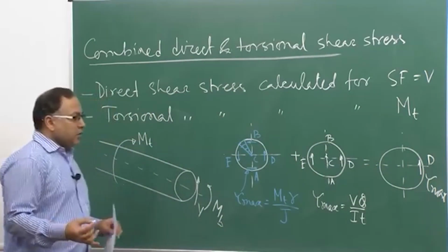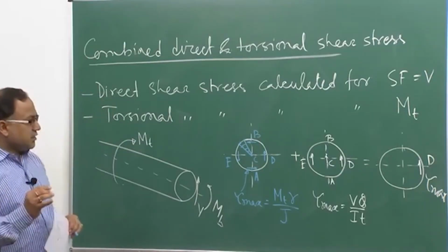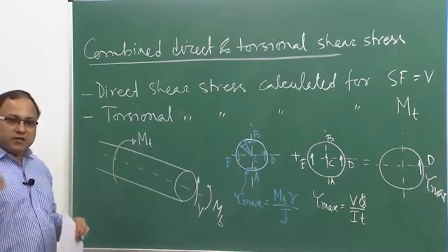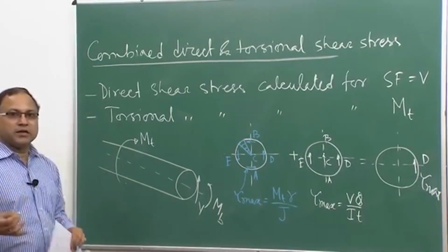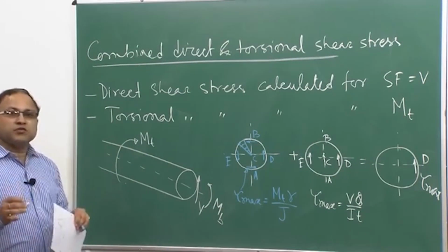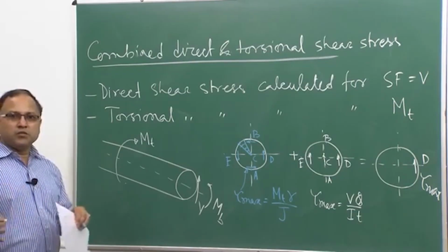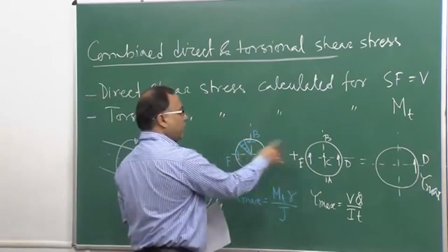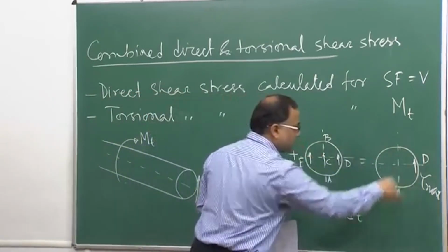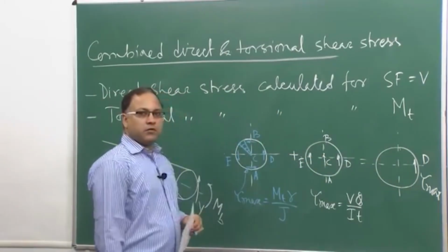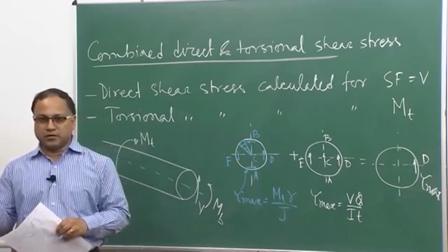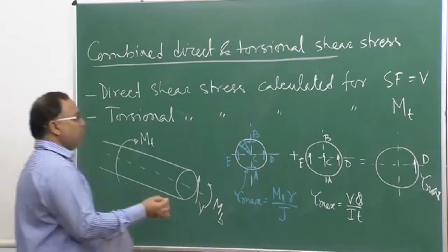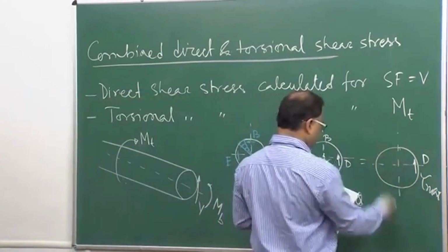So, this kind of situation can arise when bending, shear force as well as torsion are all working together, and the method of superposition holds good because we are dealing with a linear elastic system. Therefore, we can just combine these two to get our required state of stress. So, this is my combined state of stress, fine.